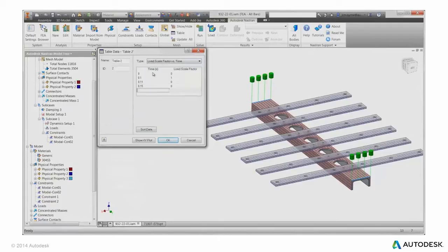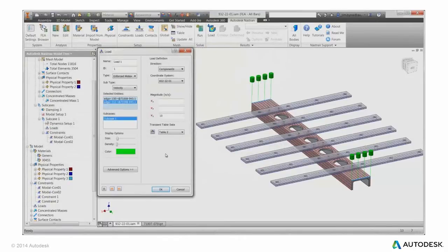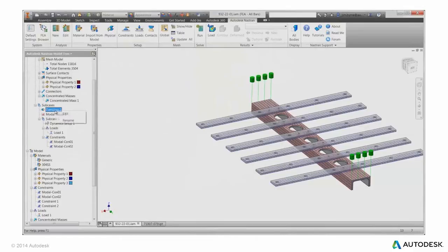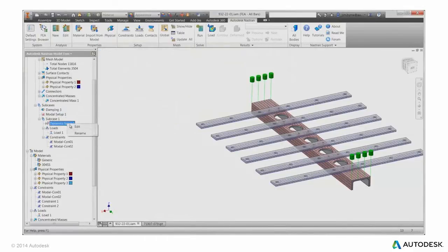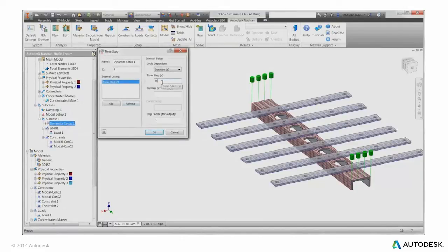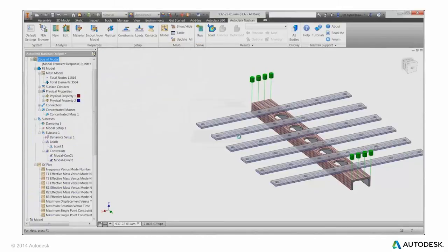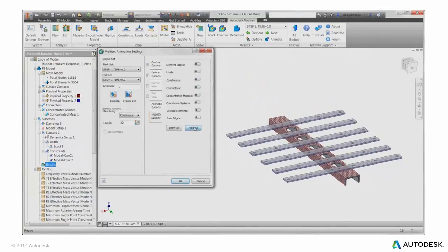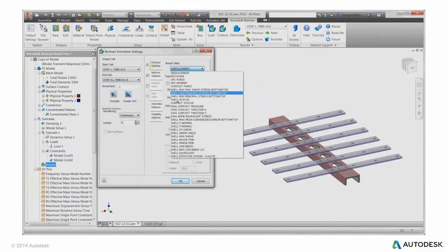We can check this visually to see what we're getting. So this C channel is going to be moving up with the arms, and then it's suddenly going to stop. So we can run the analysis with these conditions, which will only take about 2 minutes. We can choose to select time steps. We're going to have time steps of 0.003 seconds, recorded 50 times. So when we run the analysis, we can page through all these time steps. It will animate through them.